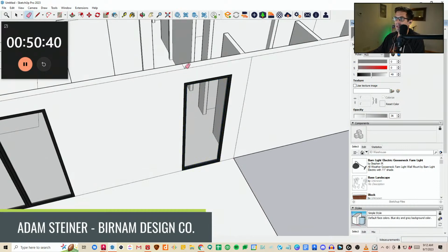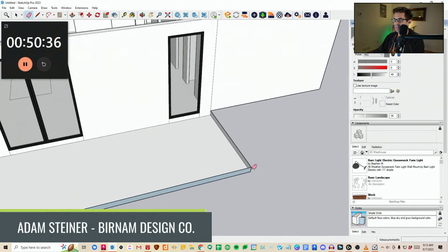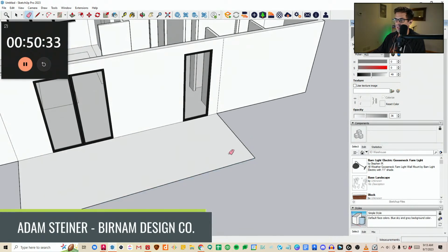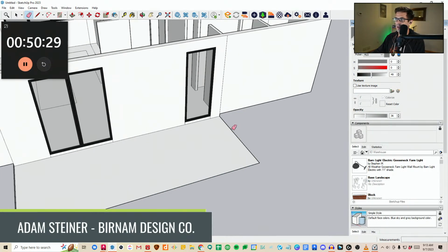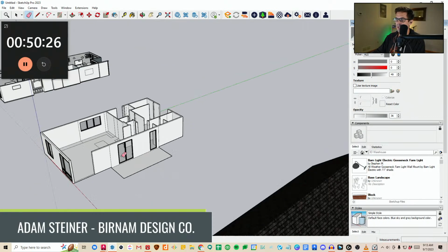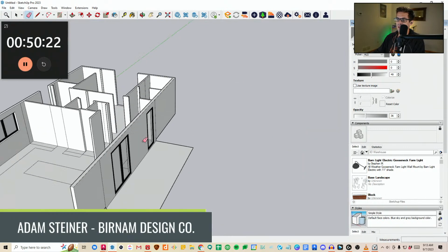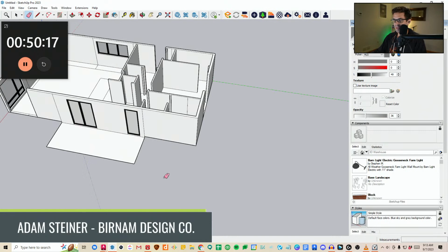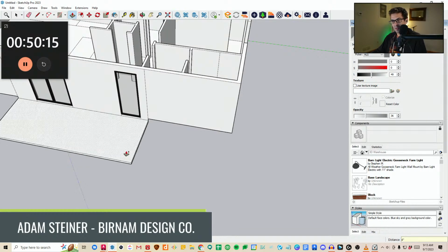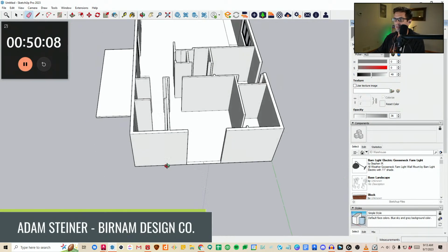So you have your main entrance, and then this is dropped. We'll drop that like 6 inches. Actually, let's drop that 4. I would maybe show this as a slab on grade home, which is not what I originally showed in this rendering. That's sitting on a post and beam structure there. But I think slab on grade will work for our purposes here. All right, and then I'm going to do a 4-inch slab there, so grade will be roughly down here, 8 inches below our floor.